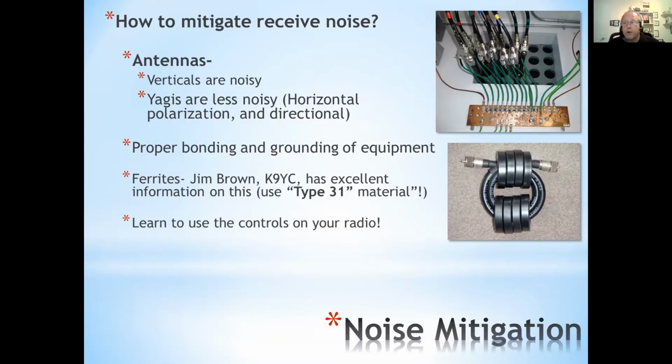And here's something we're going to talk about pretty extensively here: learn how to use the controls on your radio, right? Everybody knows that the radio's got a VFO knob and a volume knob, right? But how many of you guys have actually played with the other knobs that are on there to try to mitigate noise and how to bring in the signal and knock the noise down? A new guy coming down is going to turn his radio on, flip the switch, turn the volume control up, turn the RF gain all the way up, if it's not all the way up, and start working stations, right?